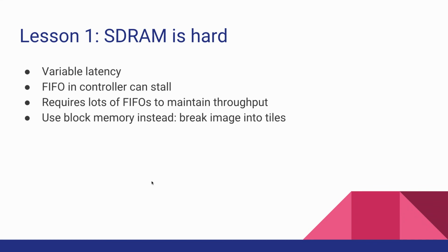In fact, I think real GPUs pretty much do that. They work on small tiles, like 64 by 64 tiles. Whatever memory they need for that, they bring it in. They do everything for the tile entirely in SRAM, or as much as possible, and then they spew it back out and go on to the next tile. So if you have a big triangle, you break it up into little tiles and do it one at a time. Then you don't have to worry about any of this variable latency of synchronous DRAM.